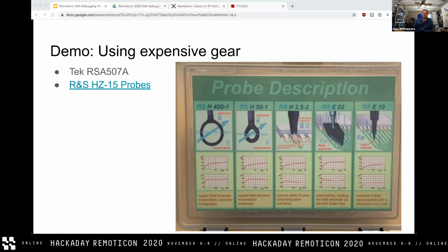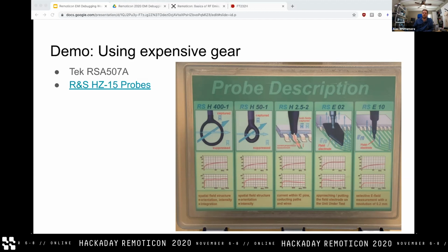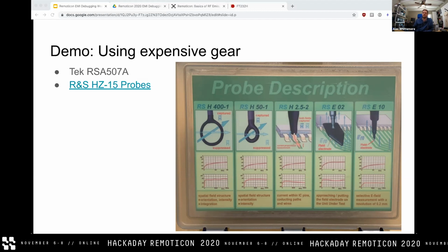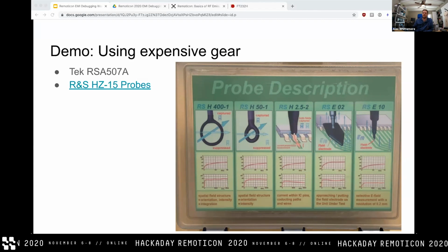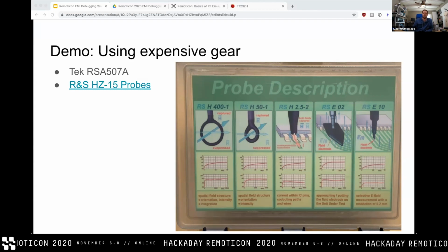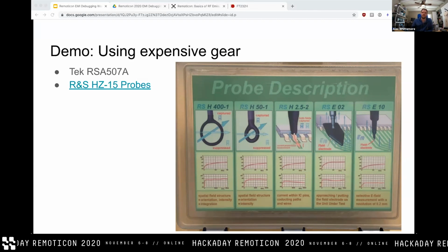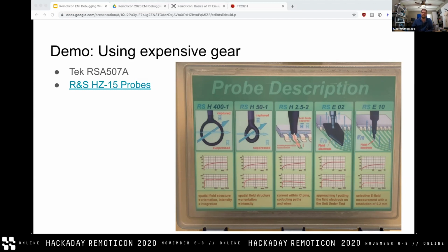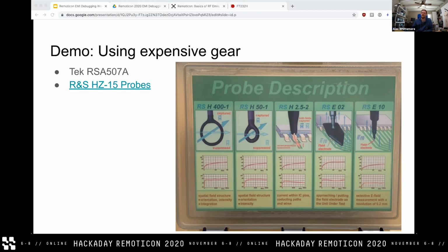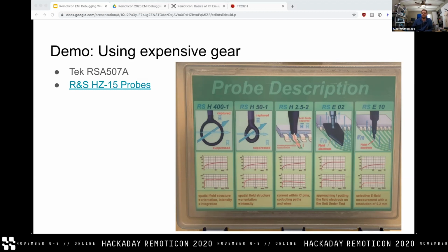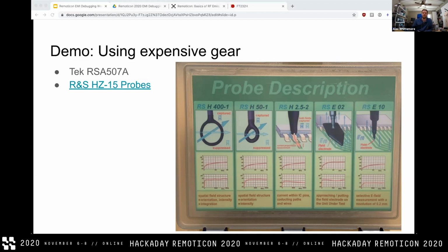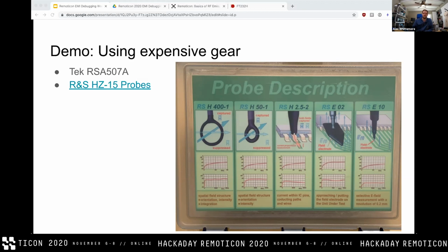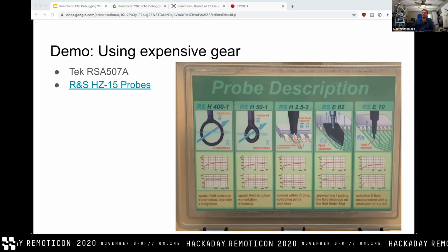This is exactly the same way that a voltmeter senses voltage and a current clamp senses current by virtue of magnetic field. We've literally got a current clamp that uses air as the core for all of these H-field probes. And we've got, I don't want to say electrostatic, but basically a voltmeter operating in air, which is a little tiny antenna on the end of each of these E-field probes.